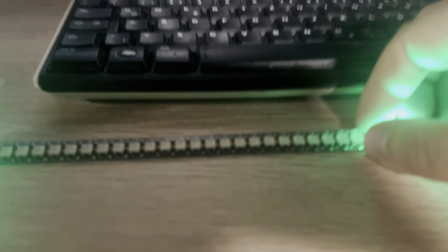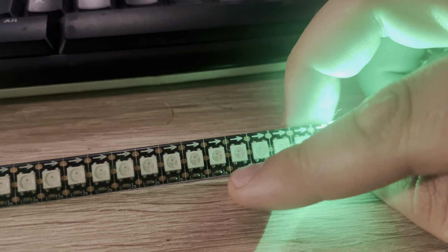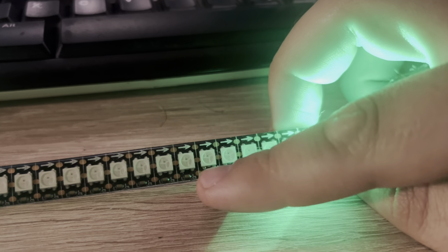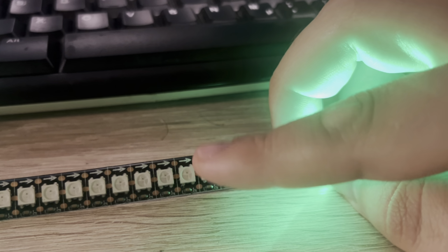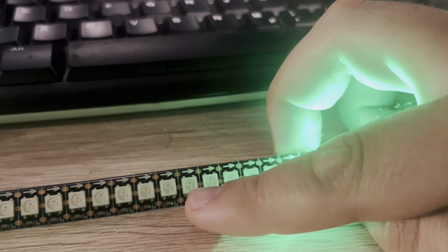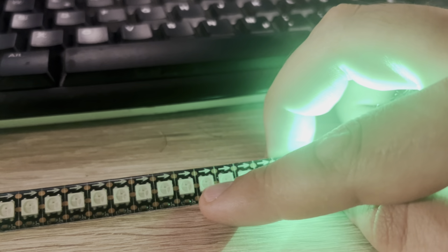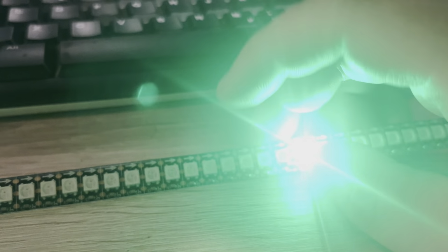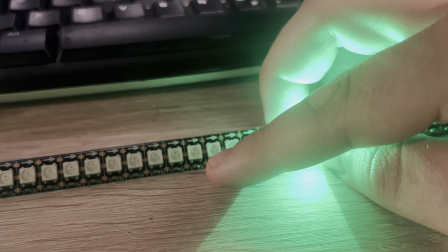So it's like a shift register. The LEDs are shift registers, so you can cut them at any point that you want. And every single LED has these 3 pins, in and out. So the ground and 5V will only go in. And then there's a data input and a data output pin. And the data output pin from one LED goes into the data input pin from the next LED. And what you finally achieve with this is a shift register.